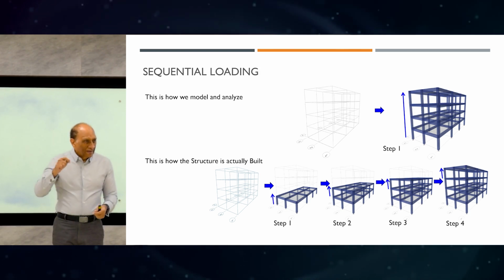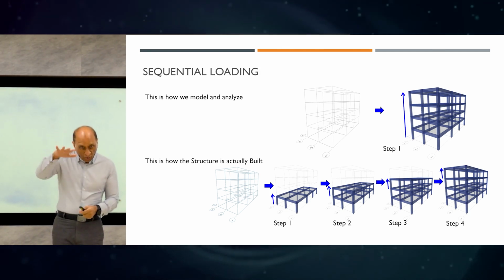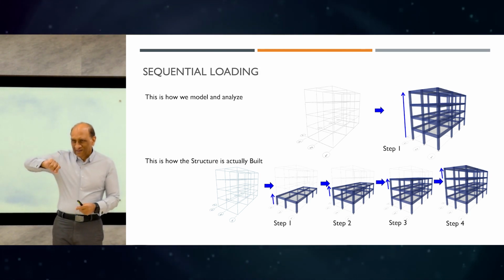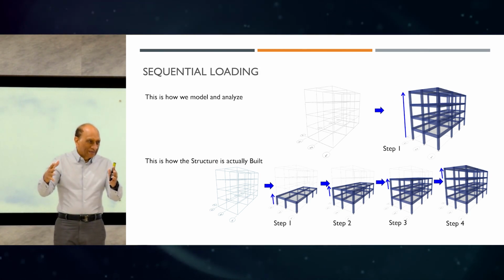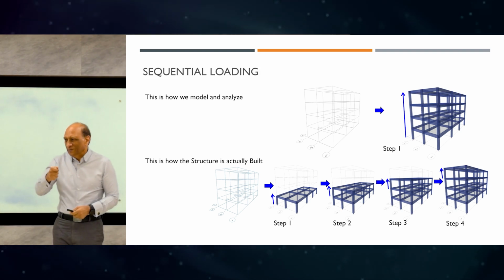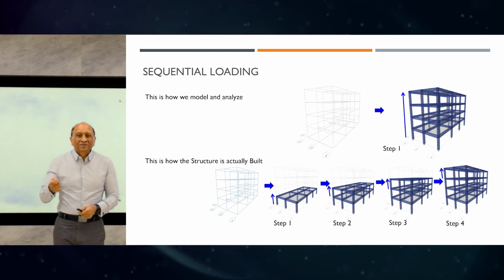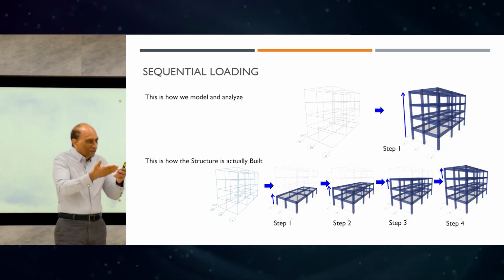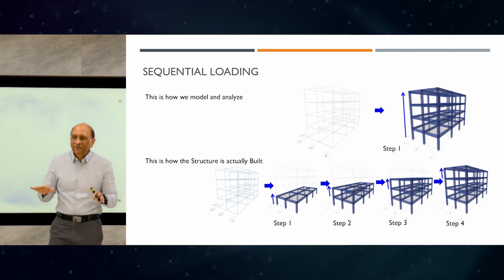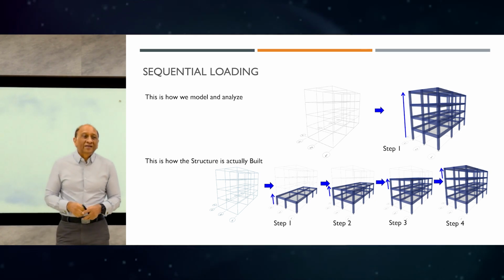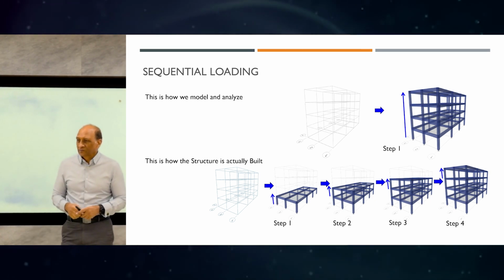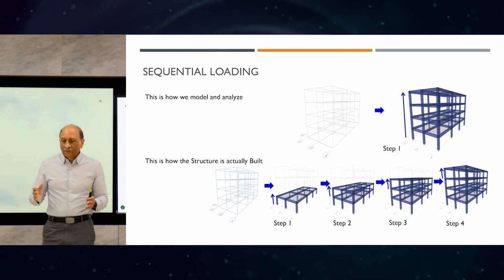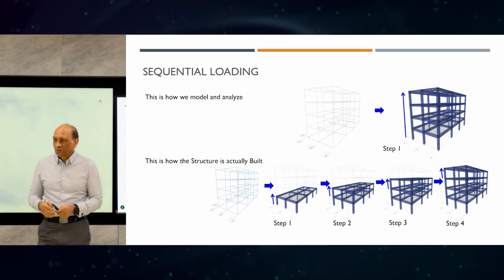one time and then apply all the dead load on all of the building at one time, as if the building is there without weight, and suddenly you switch on the weight at one point. And this is not the same as constructing the building floor by floor and loading floor by floor. The two are very different. They will create very different distribution of forces, internal forces and displacement. And if we don't manage this, you cannot predict the real response of the building.